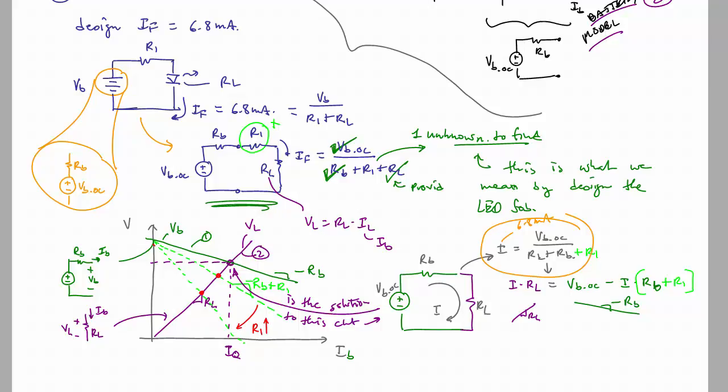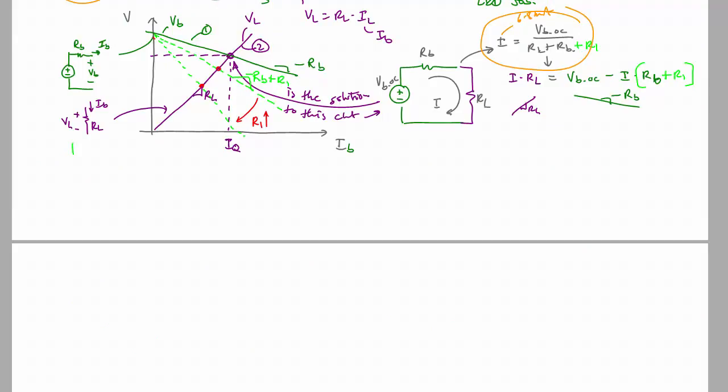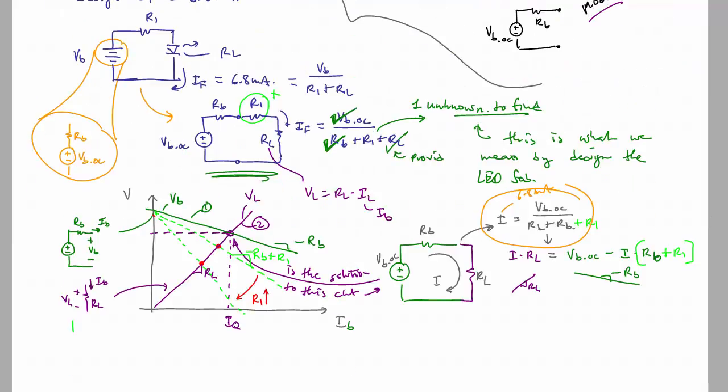Now it's the load line for the battery plus, let me augment that, it's going to be the battery open circuit voltage plus RB plus R1. Okay, so that's our Thevenin equivalent source for our battery plus this external R1 resistor. And now we have something that we can turn, right? Whenever you're asked to design something, you have to have some variable that you can adjust in order to meet the requirements. The variable you can adjust in this case is the value of R1, this one external physical resistor that you're going to place between the battery and ultimately this LED.